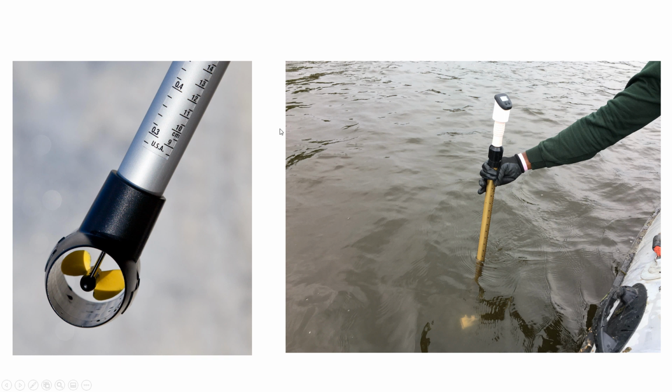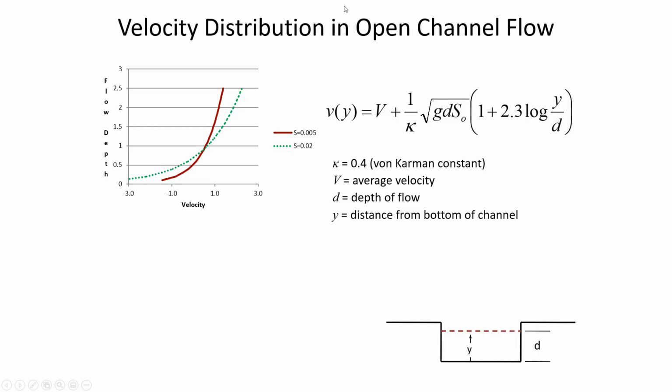So this is one way to find out what the water velocity is, but the water velocity changes as a function of depth. The velocity may be relatively fast moving up at the surface where there's not resistance, and slow moving down beneath. And there's a couple of different formulas our book introduced for calculating and estimating the velocity distribution.